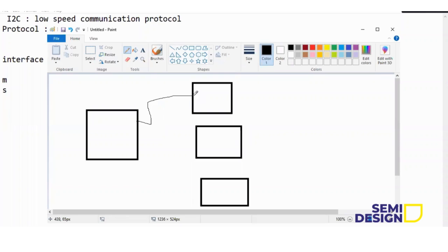Now my question is, in the I2C master I have two lines, one is SDA and one is SCL. The SDA is a 1-bit line, and I have 8-bit data to transfer. I am doing the address transfer first. The master will send the address to the slave, then the slave will send the response back to the master. How does this happen with a 1-bit data line?